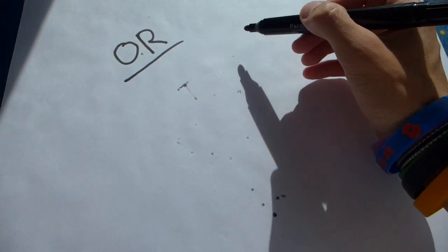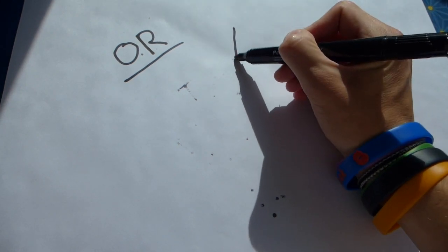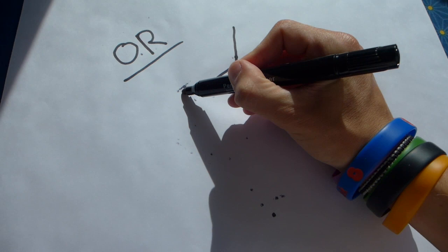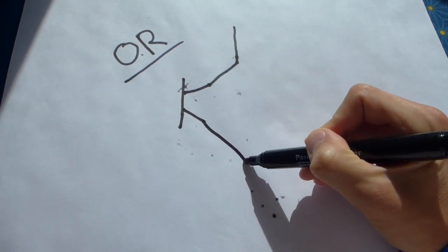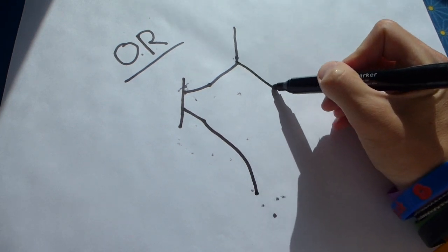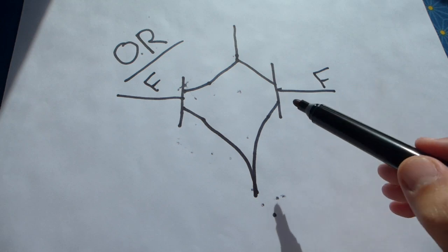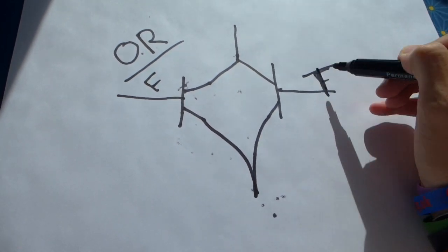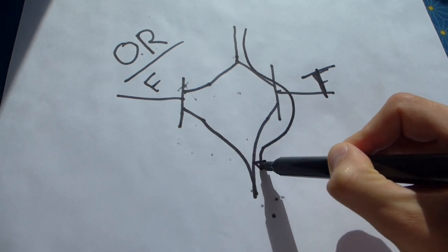Finally, we need to build an OR gate, an operation to test if any of our inputs are high. Again, we need to take a transistor for each input and organize them in a parallel circuit, where the output is the point where they all converge. If any single one of our inputs is high, current is able to flow through and output high.